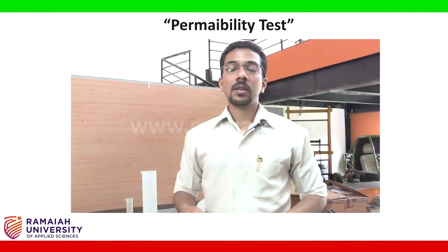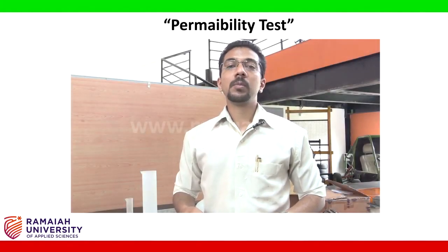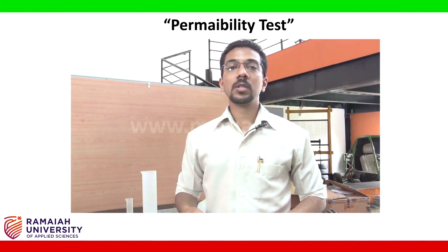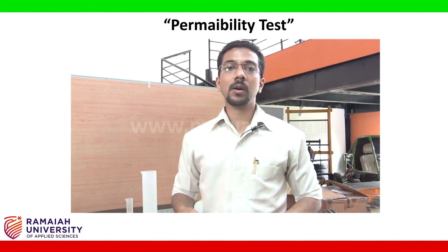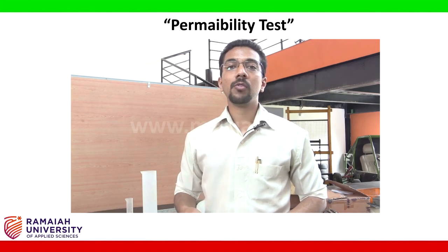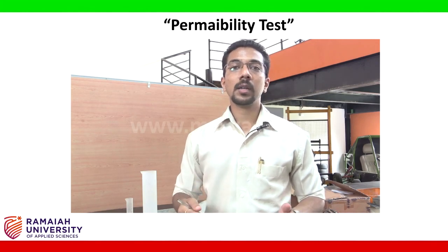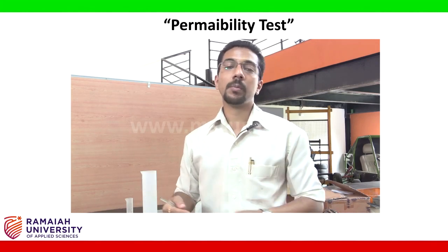Hello students, today we are going to study about the permeability test. This test is as per IS 2720 part 17. The test is required to find out the coefficient of permeability for both coarse grained pavement material as well as the fine grained pavement material.